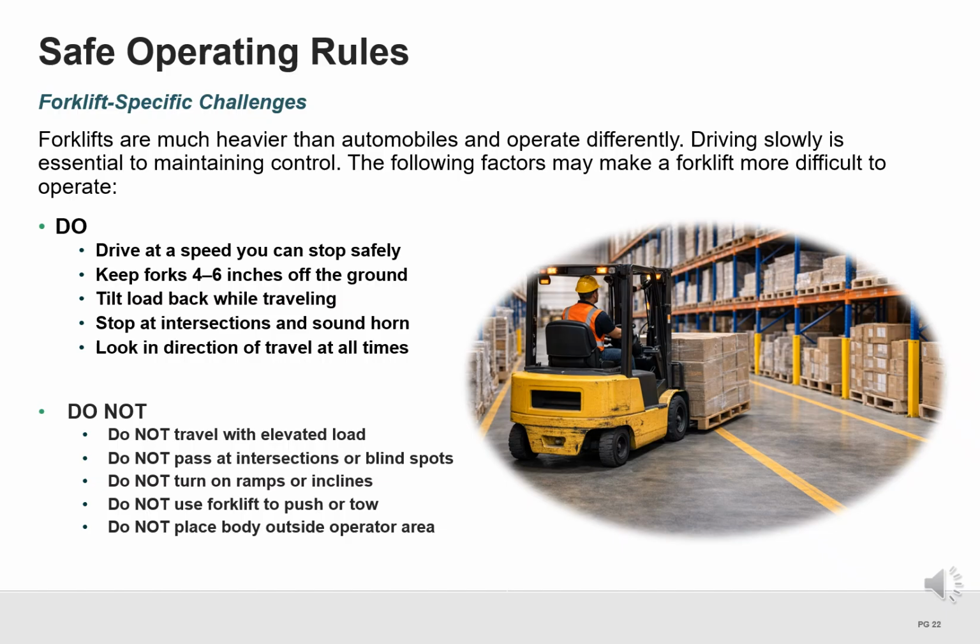There are also actions that must be avoided. Never travel with an elevated load, pass at intersections, or turn on ramps. Do not use the forklift to push or tow, and never place any part of your body outside the operator area. Following these rules helps maintain control and prevent serious incidents.